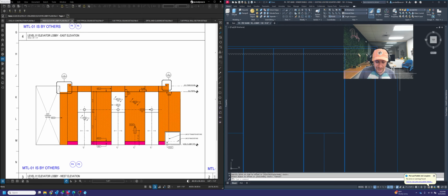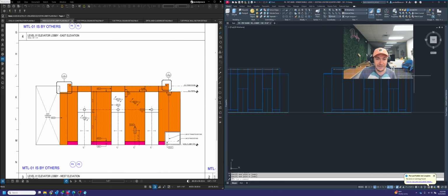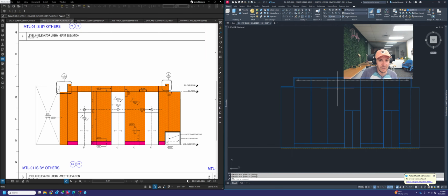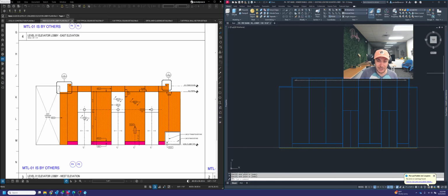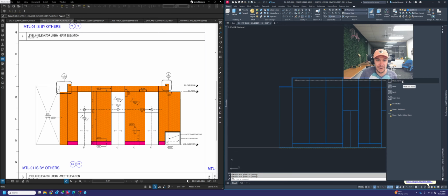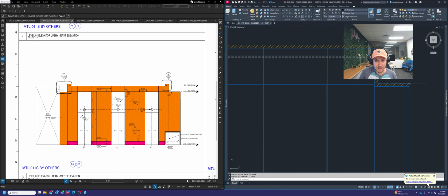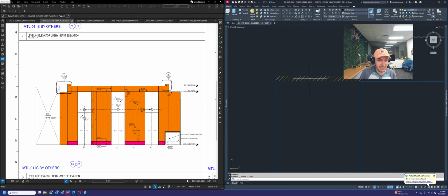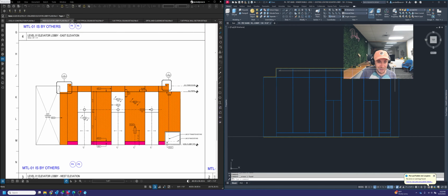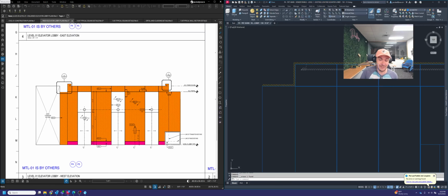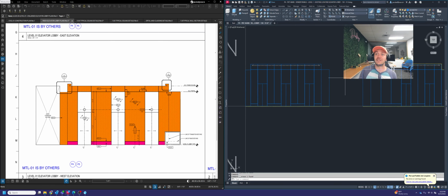All right, and then I'm going to close the polyline by throwing in a couple of extra lines at the end to cap it off. And the last step that I want to do is hatch it. So we're going to go into our hatching tool palette, and we're going to drag and drop that in. Last thing you're going to do is, just like the floor hatch, you don't really need the outside lines. In fact, I would suggest deleting them like I just did there, just to show that there is a ceiling there, but it doesn't need to be the thickness of the ceiling or anything. It's just to represent that it does exist up there.